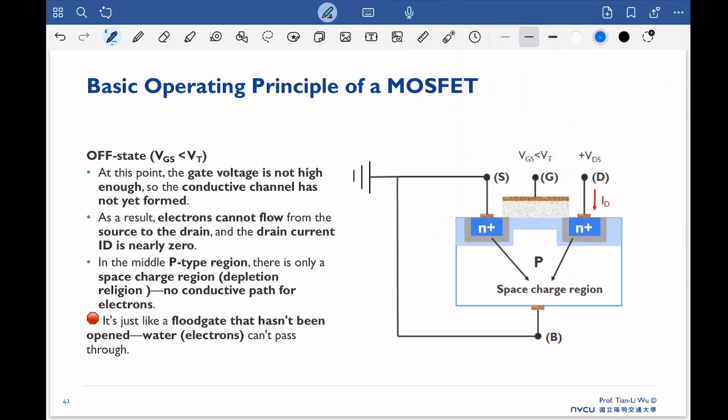So in the beginning, as I said, what we're interested in is the drain current versus the gate bias. This is the condition of the gate bias: we start to increase our gate bias a little, but still below one criterion that we call the threshold voltage, VT. At this moment there are no electrons here, so we can expect that our current is equal to 0. So ID is equal to 0, and this is our criterion that we call the threshold VT.